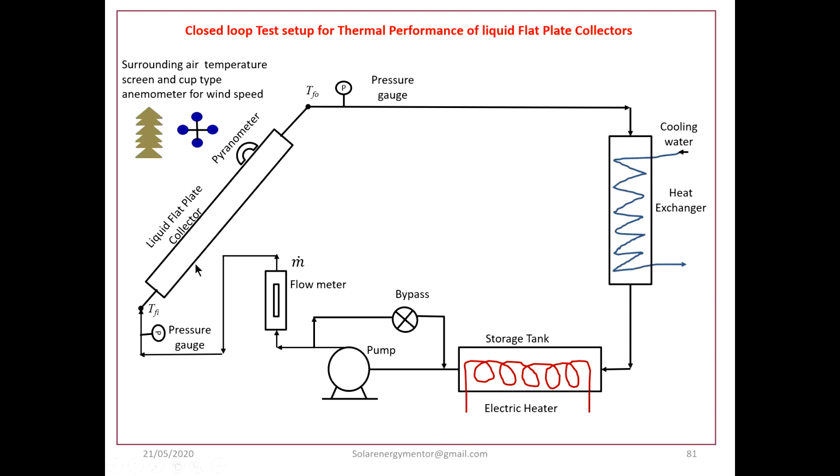If the collector needs to be tested at TFI 75 degrees Celsius, then water at 75 degrees Celsius is heated here, and that water is supplied, so that at TFI 75 degrees Celsius, what would be the performance? So that is the purpose of the storage tank, which is provided with an electric heater to vary the temperature of the fluid entering the collector.